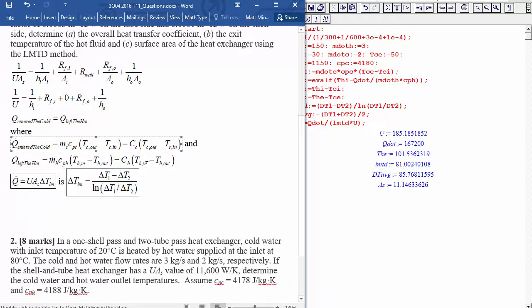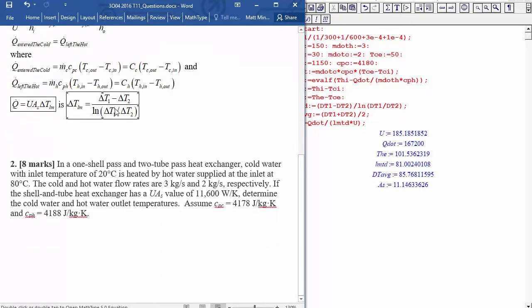Now from the series of these other equations, sure, we know the inlet conditions in each of these, so we sort of have 1, 2, 3 equations and 3 unknowns, and in principle we can solve it, but the log mean temperature difference is so coupled in things that this is difficult to use. Plus, the log mean temperature difference that we calculated for a pure parallel or counterflow, is it going to be working exactly the same for this kind of a heat exchanger?